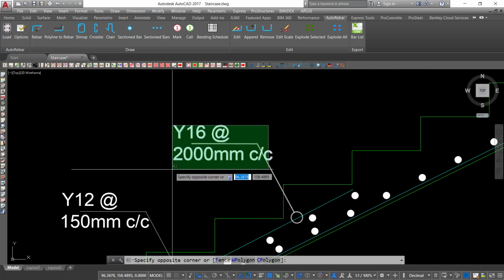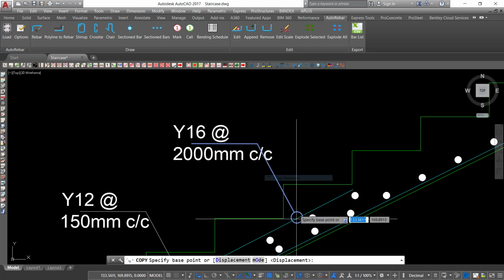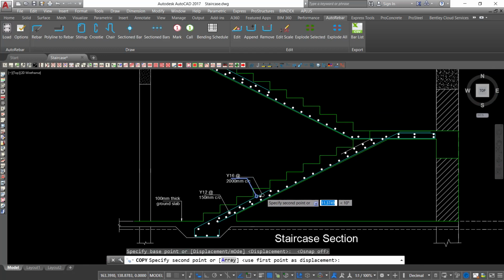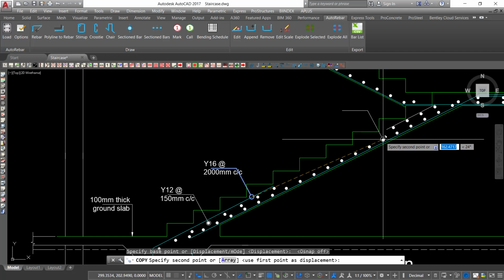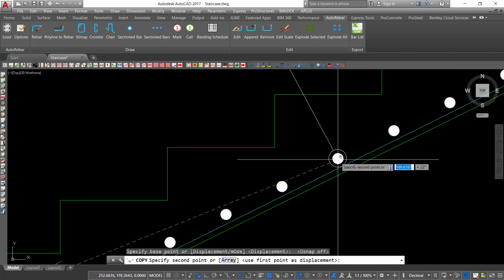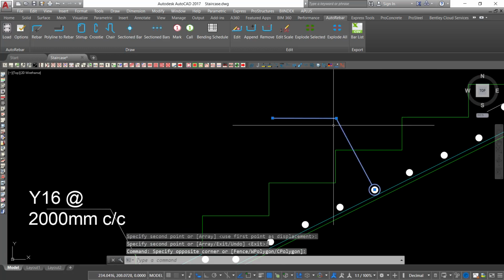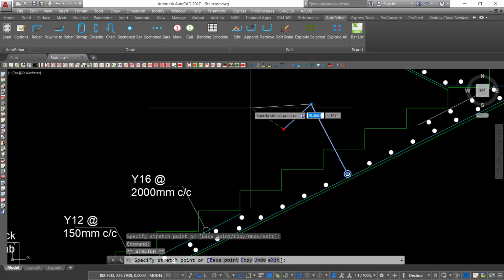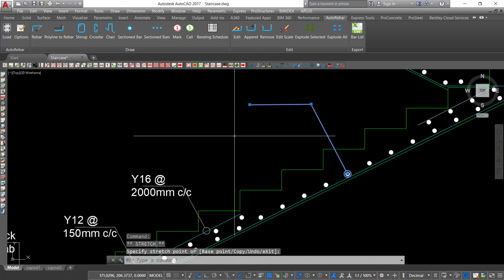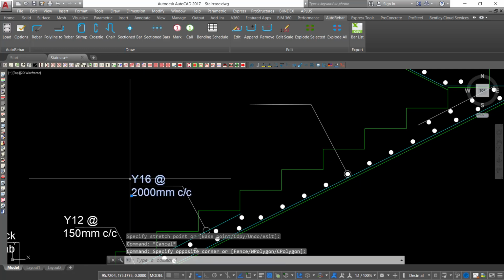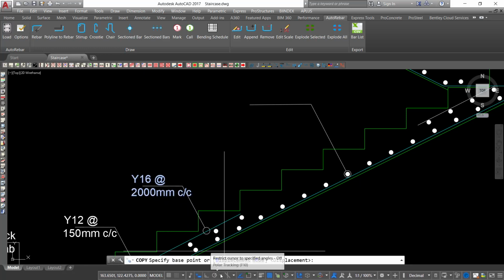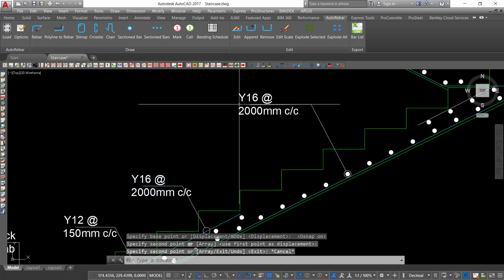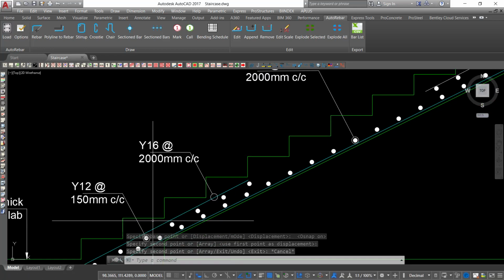We are going to pick everything here. Pick the arrow first and select copy, and you'll pick on this. First of all, always disable and enable ortho so that it doesn't mess you up. So I'll pick on this one and give it a description, and drag this one slightly up somewhere there so that we get some space. I'll terminate it right there. Then I'll pick this same text, and to be more accurate, I'll pick it from that snap and snap it right there. I'll give it a description of Y12 similar to this Y12.